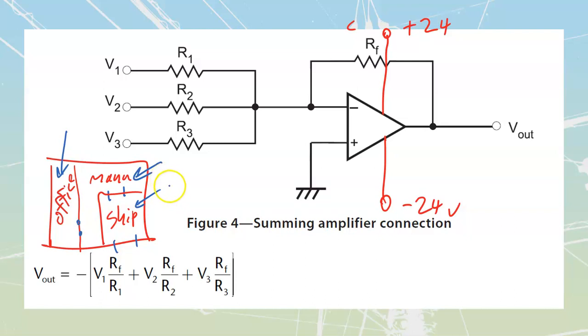So what we'll do is take each of these temperatures. We'll call this one temperature 3, this one temperature 2, and this one temperature number 1. I'm going to feed them into inputs 1, 2, and 3, those values of voltage that I'm getting from there. Then I'm going to weight them differently. By adjusting the amount of resistance across each one of these, I'm going to be able to adjust the amount of weight that is given to the signal.